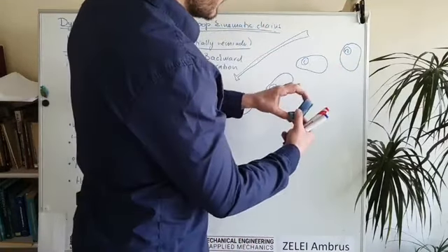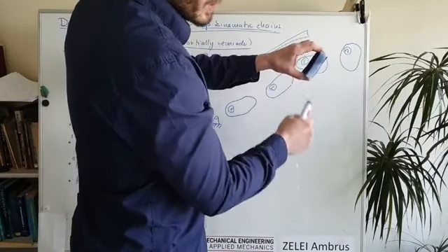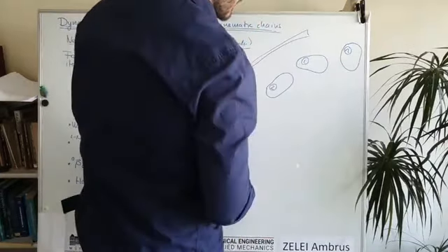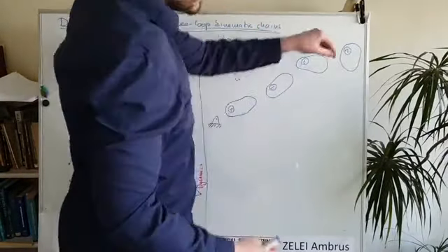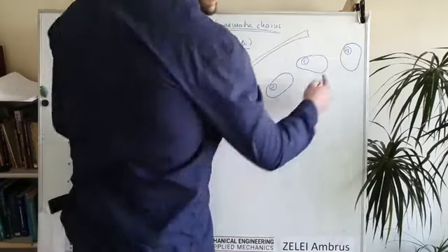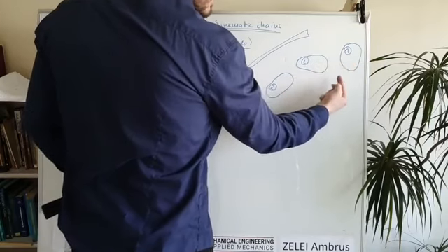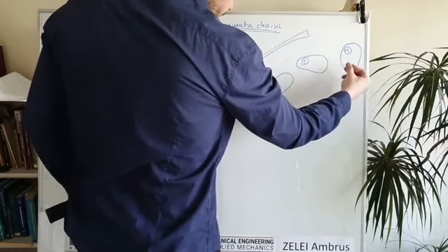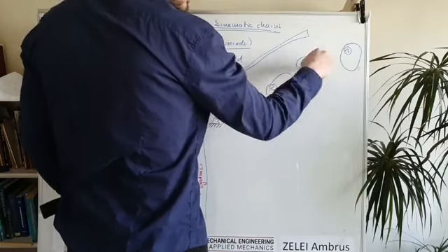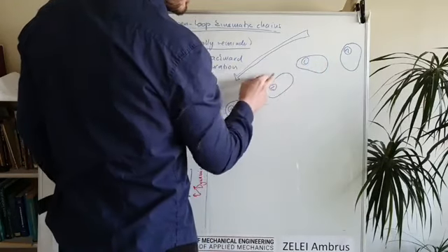I can consider the weight of the sponge, and this gravitational force acts on the last link of the robot, and then I will be able to calculate the joint torques and joint forces. The joint forces acting on rigid body N, the reaction can be put here on the previous joint, and therefore I can again calculate the joint forces here.